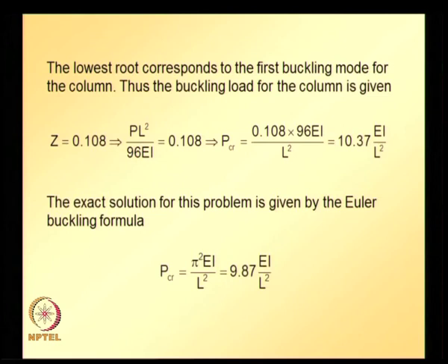So this is the theoretical value of critical load for this particular column with pin end conditions. Whereas when we apply the finite element method with 4 linear elements, we obtained P critical as 10.37 EI over L square.